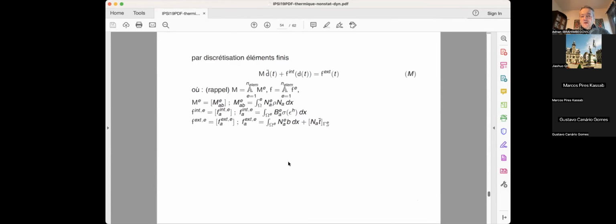So then when I'm doing my finite element approximation, I still have the inertial term, which is linear. It's just mass times acceleration. The fact that I have nonlinear constitutive behavior, like nonlinear elasticity, does not change this. We don't care what the behavior of the material is. If I take it in the inertial term, this is the inertial force, it's just proportional to the mass. And the only complexity is that you have the internal force being a nonlinear function.